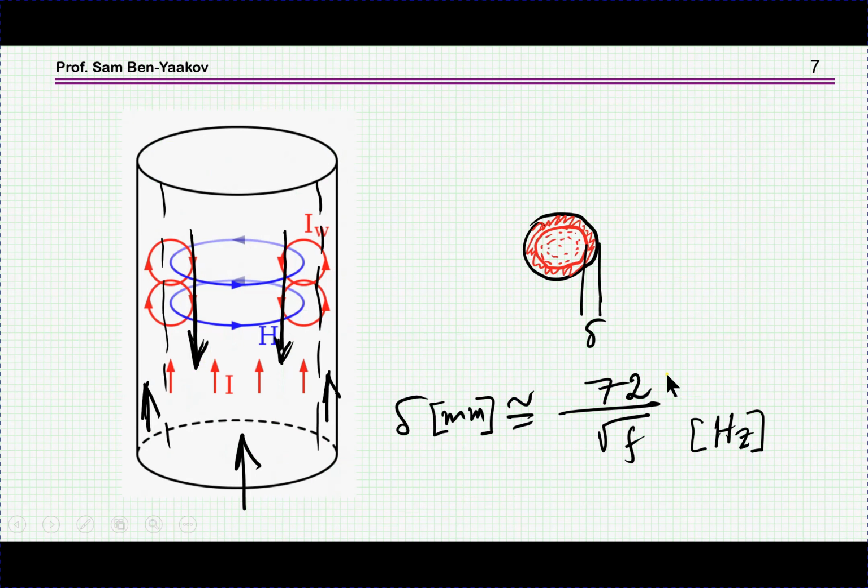The skin effect is something very similar, except it's not an interaction between two wires, but rather the interaction of the wire on itself. So if we have a current going in this direction, then we are going to invoke the magnetic field, which in turn will cause eddy current. And now what we can see is that on this end here and here, these currents are being added to the current going this way, and in the middle it's going to be subtracted from this current.